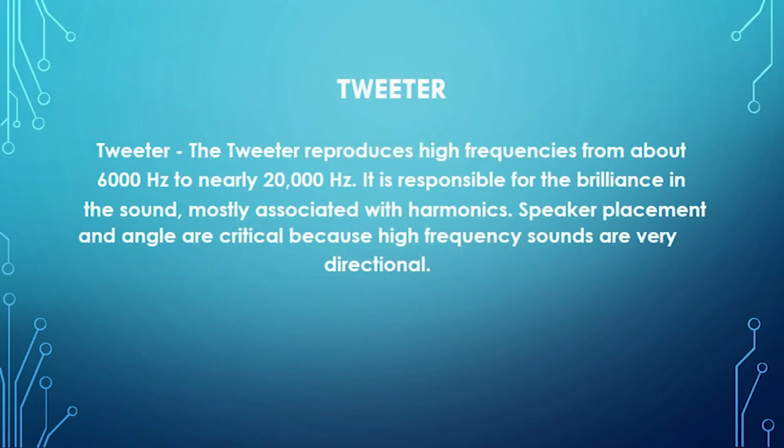2. Tweeter. The tweeter reproduces high frequencies from about 6000 Hz to nearly 20,000 Hz. It is responsible for the brilliance in the sound, mostly associated with harmonics. Speaker placement and angle are critical because high-frequency sounds are very directional.